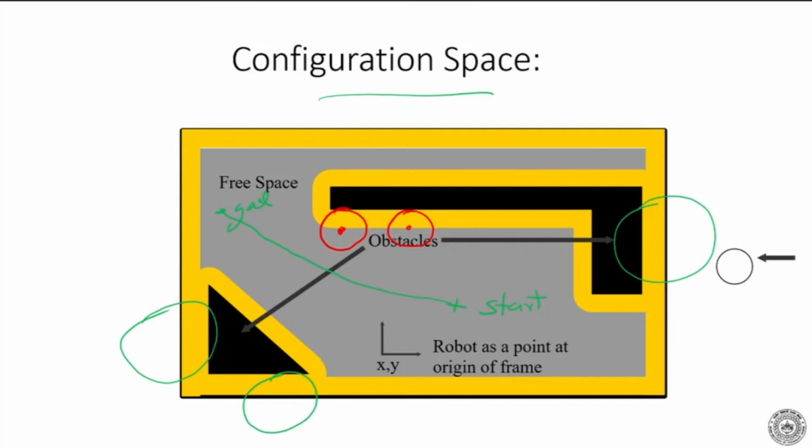So what it basically did, and what you can imagine and guess by now, is that before starting our planning algorithms, we can come to the configuration space and convert the robot to a point, then plan the path for a point robot. So we're finding the path for a point robot. And the other thing that also becomes very clear from here is that the configuration space looks like the Cartesian space, but it is not the Cartesian space.